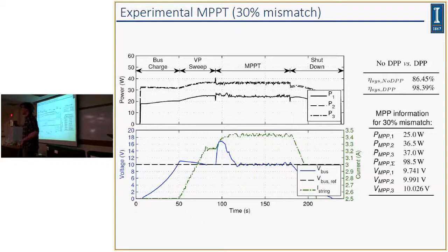Maybe you mentioned that this is future work, but when you adjust the string current, how close does that stay to the optimal string current? Or does that even matter? Yeah, so that would induce ripple in the output, right? Exactly.